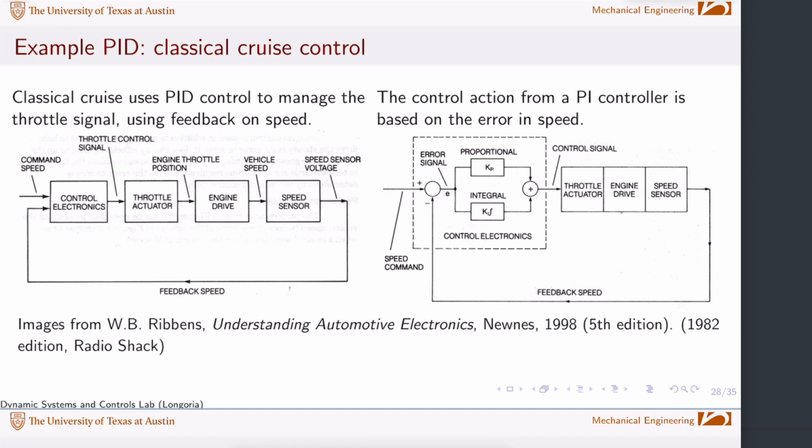Finally, derivative control, which is not included here, is really good for adding damping to the system. You look back at the slide where I introduced the three terms. I didn't go over it, but it talks a little bit about the effects of each of these. The derivative term, think of it as almost like adding some damping. And remember, derivative is like looking at the rate of change of error. So it kind of is anticipatory, and it can add a damping effect in your system. It's a very simplistic way to look at it, but that's effectively what it does.